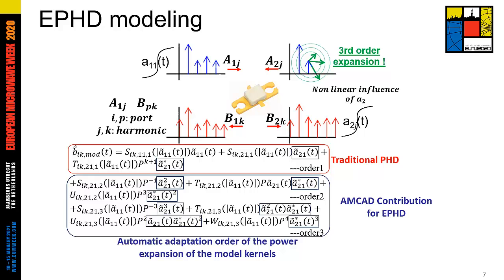So what does that mean? It means that instead of having one model for one impedance and seeing a linear variation or linear influence over a very small area around the impedance, we're going to create a model for a pattern of impedances which will have a nonlinear influence over the whole pattern. So our equations are nonlinear and are able to predict the response of the circuit over a large area on the Smith chart.